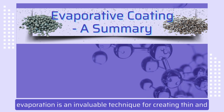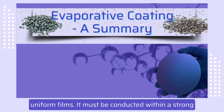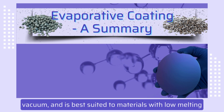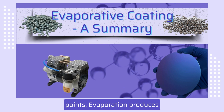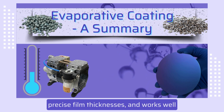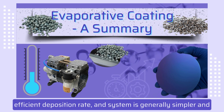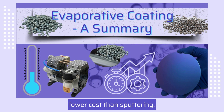Overall, evaporation is an invaluable technique for creating thin and uniform films. It must be conducted within a strong vacuum and is best suited to materials with low melting points. Evaporation produces precise film thicknesses and works well on flat substrates. The technique offers a high and efficient deposition rate, and the system is generally simpler and lower cost than sputtering.